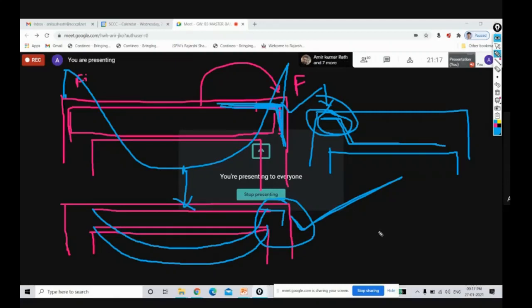May I add some points, sir? Actually, in IS 456, it is mentioned that if the diameter of the bar is going beyond 32 mm, then we can go for weld, or else we have to provide lapping anyhow. And another thing, sir, if you want to provide the lapping at that column and beam junction, it is very difficult for the mason who is bending the bar. Execution of all these things on site is very difficult, sir.